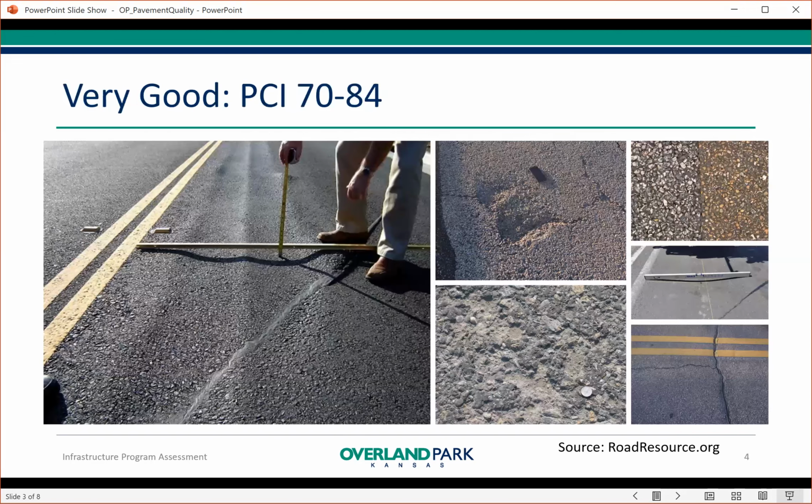A very good rating may leave an impression of a near perfect street. At this level, minor rutting from car tires becomes visible. Isolated potholes become prevalent on the lower side of the scale, and the issues detailed for excellent roads become more obvious, and the loss of surface aggregate can reach over 50%. Currently, 53% of Overland Park roads fall in the excellent and very good categories.